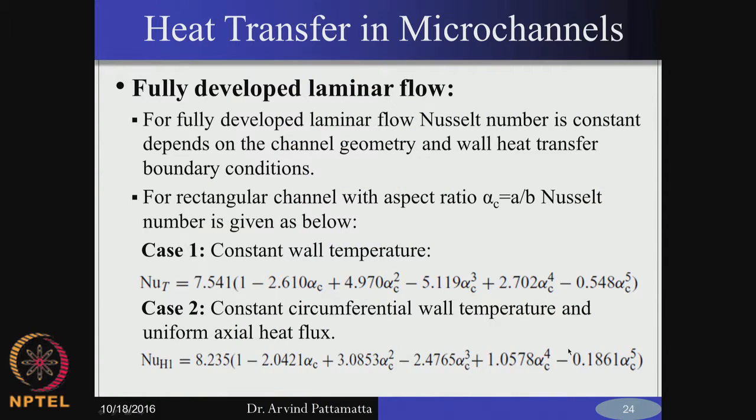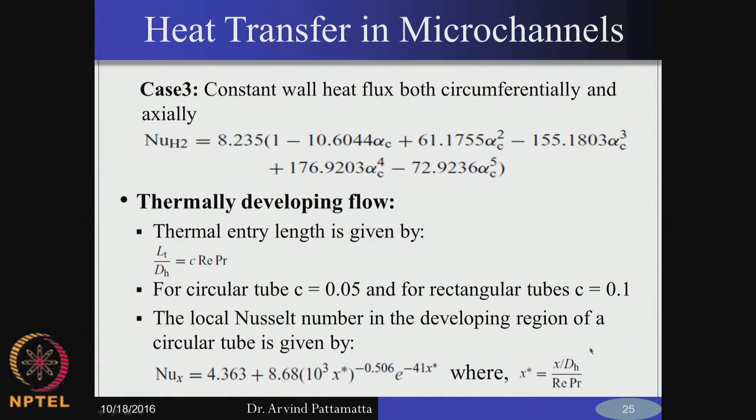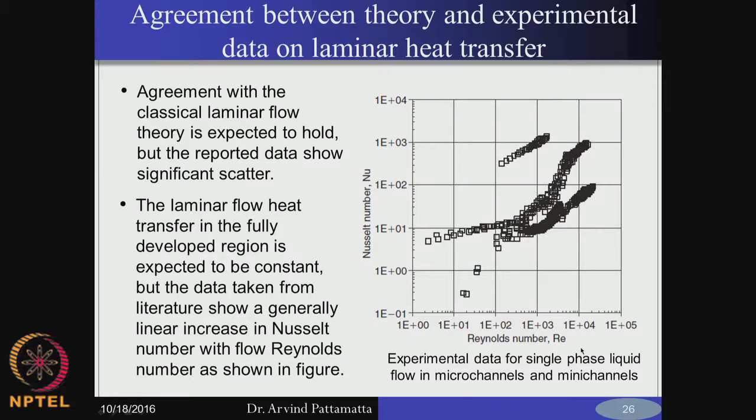They are not so easy to find, but you can make an approximation by assuming an equivalent circular hydraulic diameter and calculating it, if you do not find a suitable correlation for rectangular channels. But for the developed case you have the analytical equation. So, there is no problem.